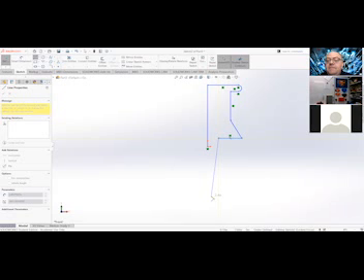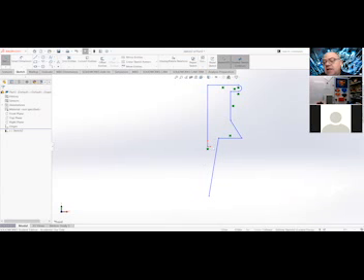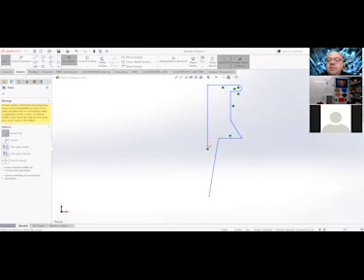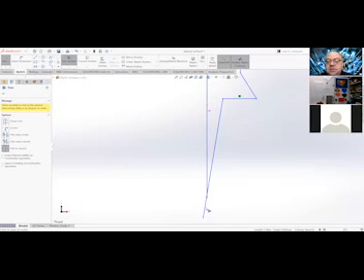quite a bit. So I embellished what I remember, and then we closed. Then they did this. Now, this isn't anything if it's not closed. And then they did a little trim work. We're just going to do an extend and power trim. So I just extend this down, extend this one over, and then trim the closest. Again, you don't want any extra endpoints. Well, then they got this.